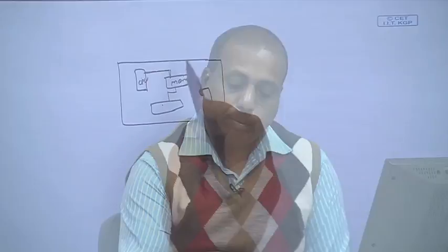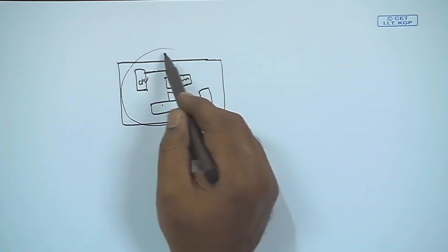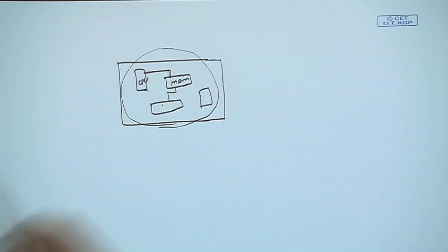Okay. So, the latency: though the CPU and memory are both semiconductor devices, it is due to the physical interconnect that we have outside the chip, which may be copper or some other metal. That is going to introduce the delay. So how do we break this speed barrier? This barrier may be broken if this entire thing is fabricated on a single die.